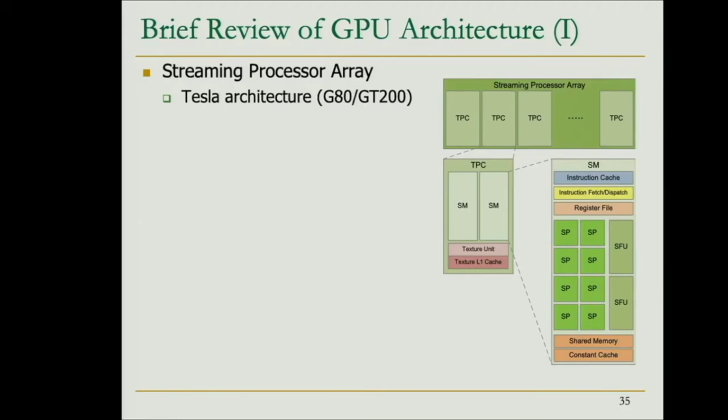This is something like the internals of each of the cores of the GTX 285. You can see inside this one, what we have is 8 of these SPs, 8 of these SIMD lanes. So what do we need to do to execute one warp of 32 threads on top of these 8 lanes? We have 32 threads in each warp.